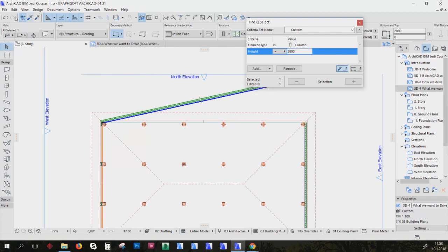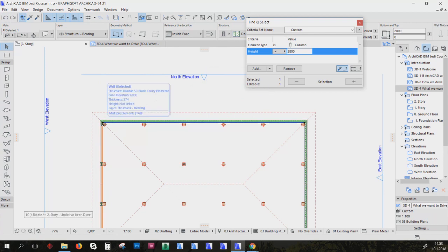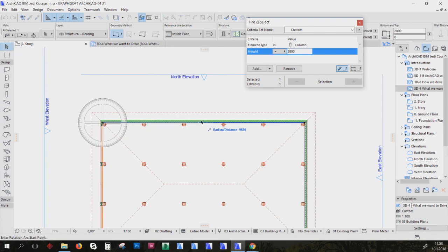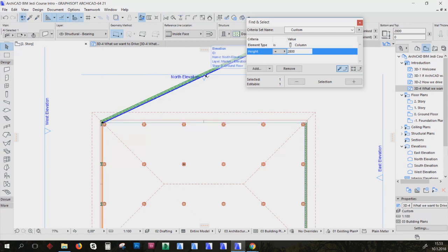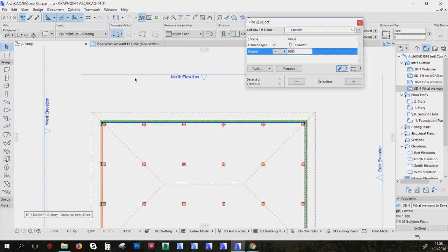That'll just move that around. And when you're doing that with Control E, if you know the angle, you then just type in A and 25 degrees, and it will poke it in at the right angle. The commands are the same, because I use them both on the same system, so it goes across all systems.